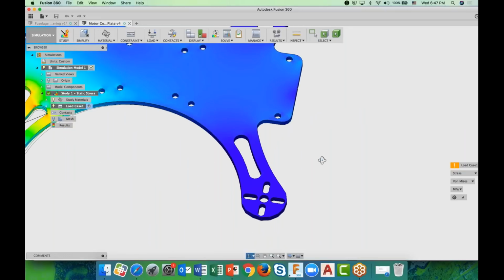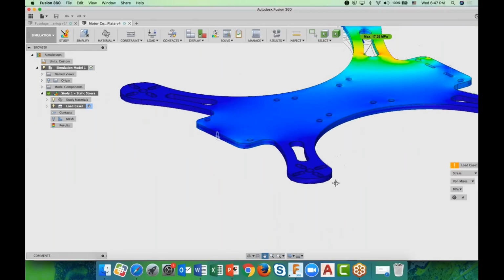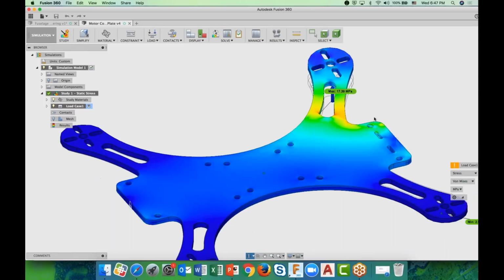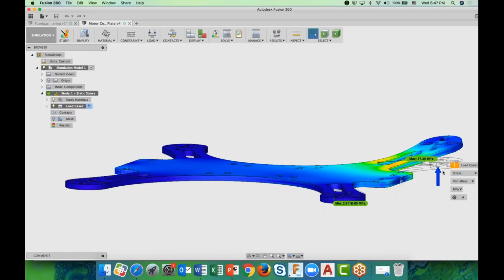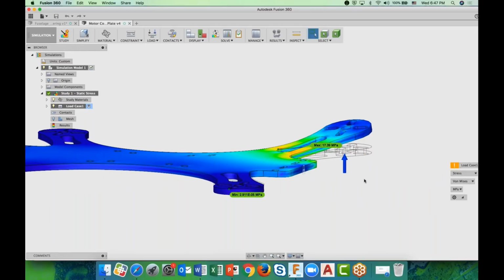And then we ran a simulation for stress, just to show you guys what it looks like. If you can find out what the force of the motor pulling up is, then you can see how this would bend, depending on whether you use plastic instead of steel. And the cool thing is that it gives you, of course, how much displacement is happening here. It's exaggerated for graphic purposes, right? It's not showing me the actual bend, but it shows you the displacement that would happen.